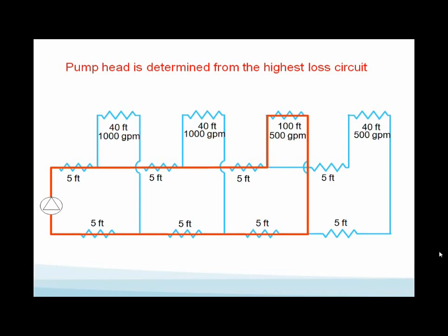You have to recognize, as a designer, which loop is the critical loop, and you've got to do the head loss calculations and detail it out and put it in the file. That was basically showing your brake horsepower at 3,000 GPM, 130 foot head at 80% efficiency. It's going to be 123 brake horsepower if you pump this direct as shown.